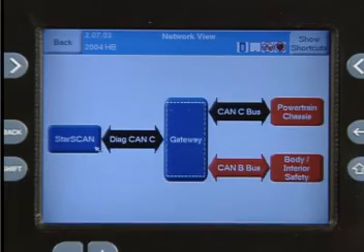The same caution holds true here as with the CAN-B bus, however. Because inputs and outputs are distributed throughout the electrical system, a problem with a component wired to a module on the CAN-B bus can affect module operation on CAN-C. Your best bet really is to trust the information you receive via the StarScan scan tool.